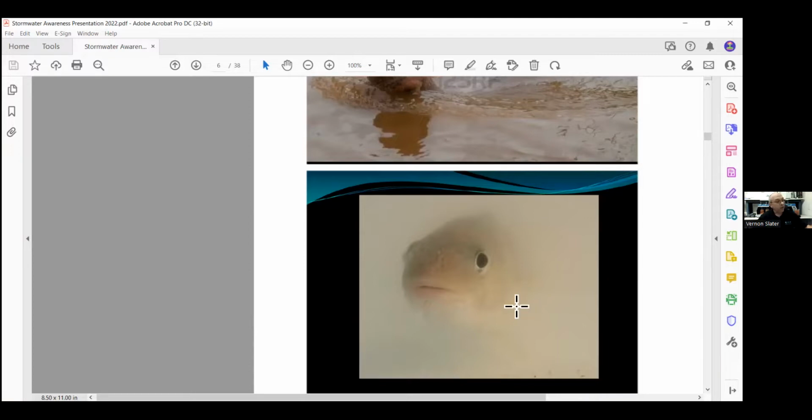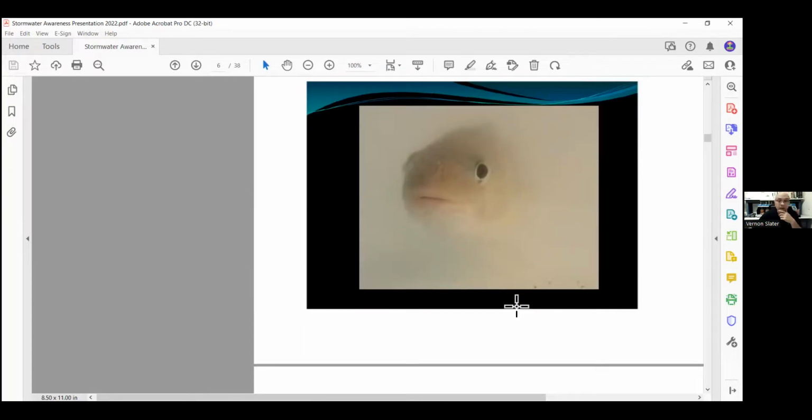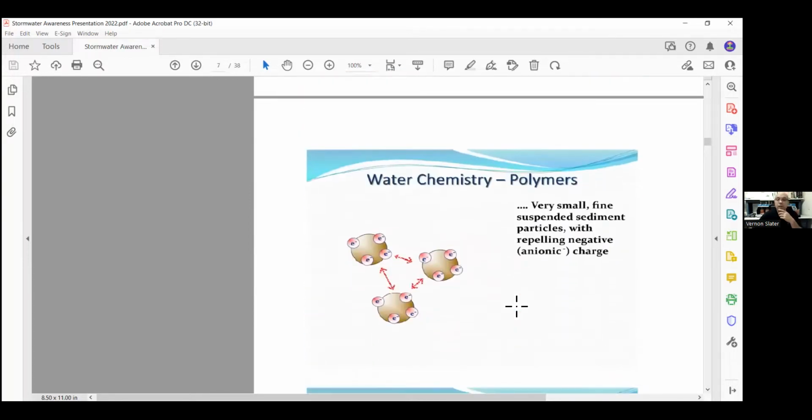And the turbidity range for construction discharge, 250 NTU with traditional BMPs. Or if you're going to have an active treatment system, then that drops to 10 NTU average and 20 NTU max. And turbid water remains dirty over extended periods of time because of 2 factors.